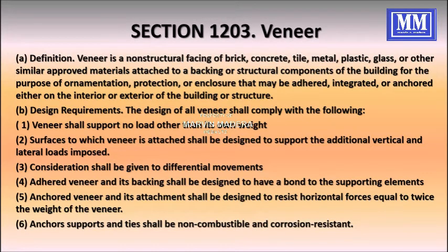The design requirement is that the design of the veneer shall comply with the following. Veneer shall support no load other than its own weight. Surfaces to which veneer is attached shall be designed to support the additional vertical and lateral loads imposed.